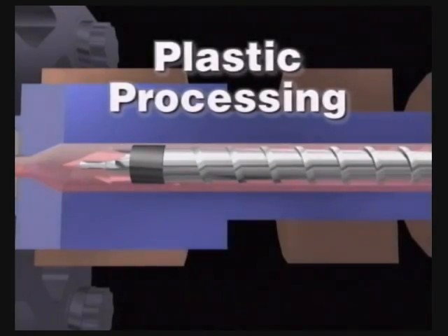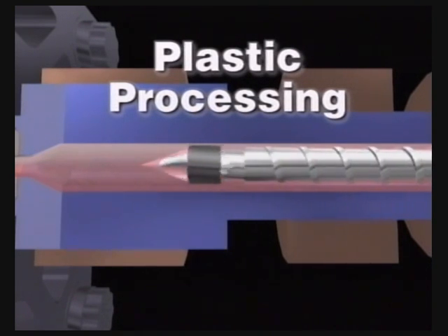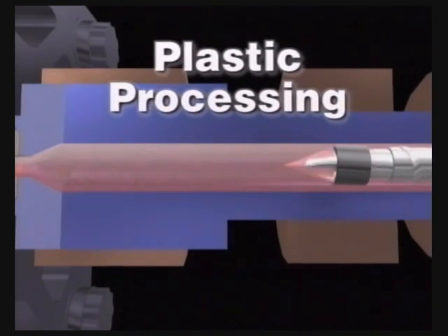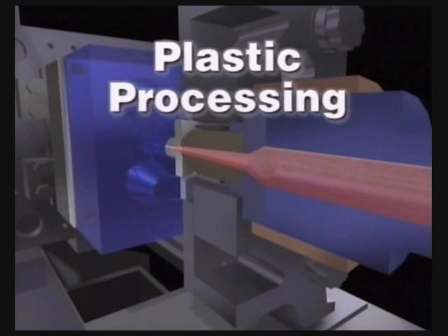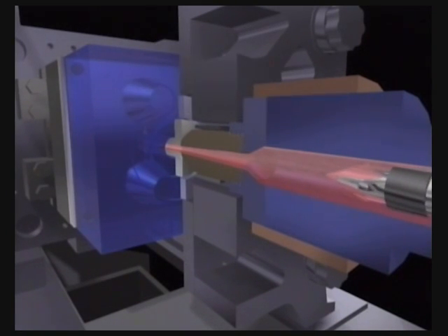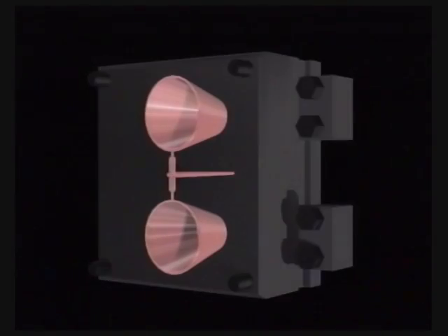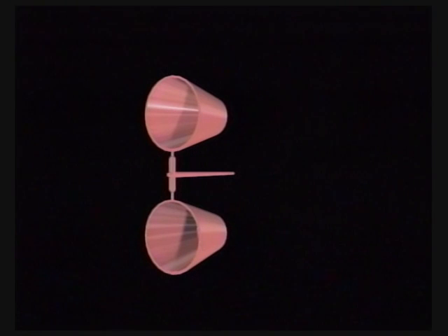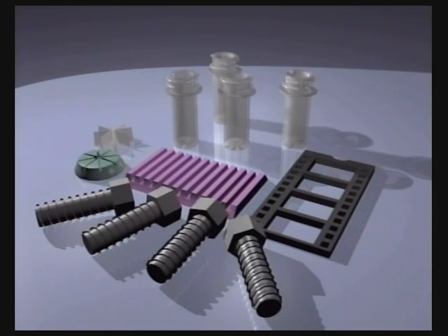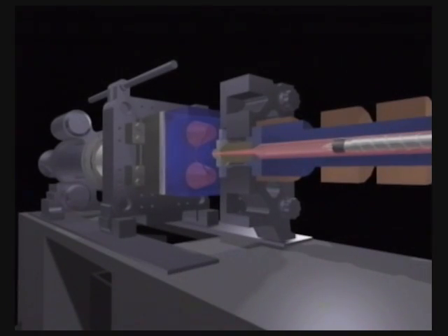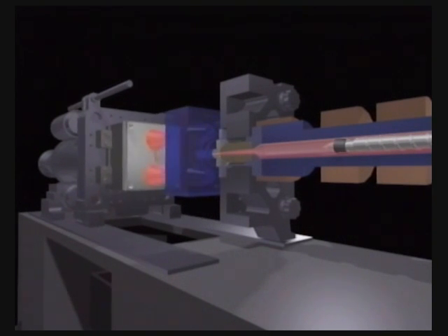Injection molding is a process by which the plastic is melted and injected into a mold cavity. Once the melted material is in the mold, it is cooled to a shape that reflects the form of the cavity. The resulting form is a finished part requiring no additional work prior to assembly, and in most cases is the finished product. Many details, such as bosses, ribs, and screw threads, can be formed during the one-step injection molding process.